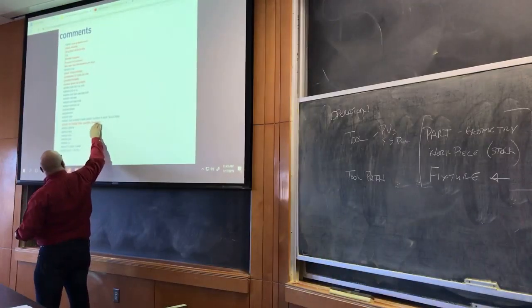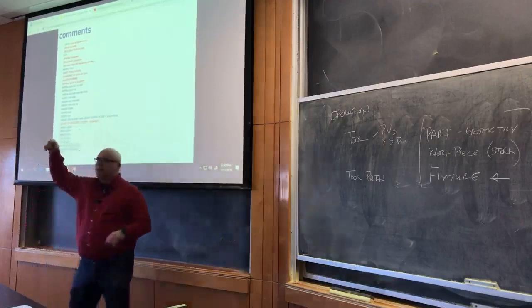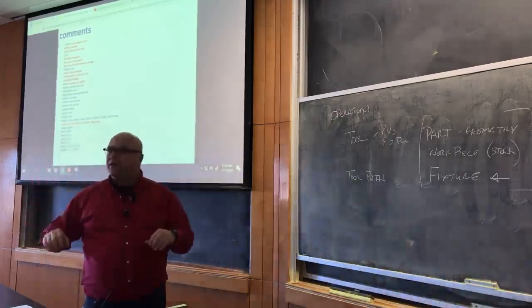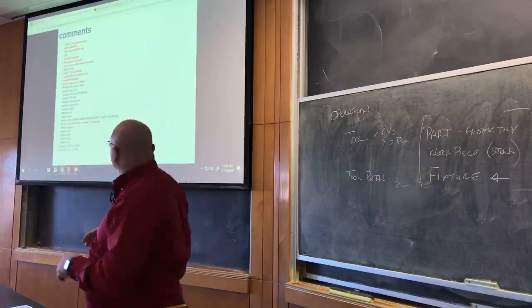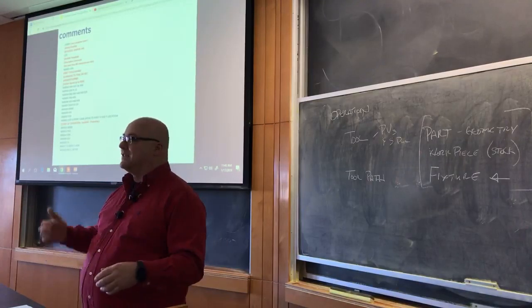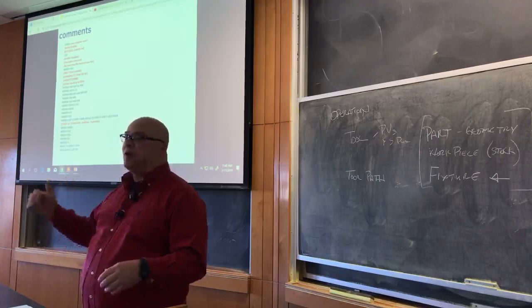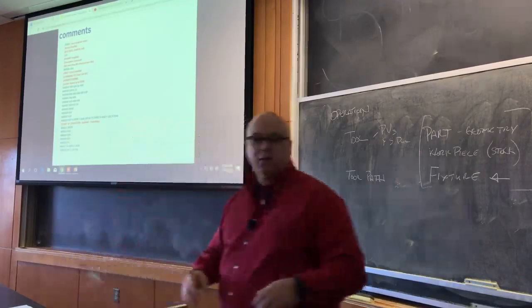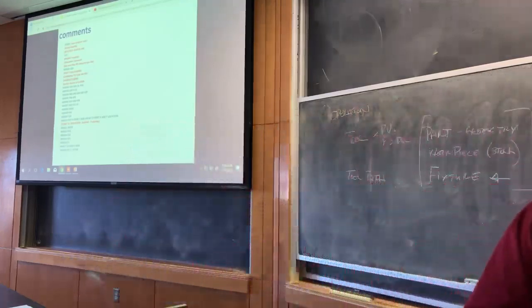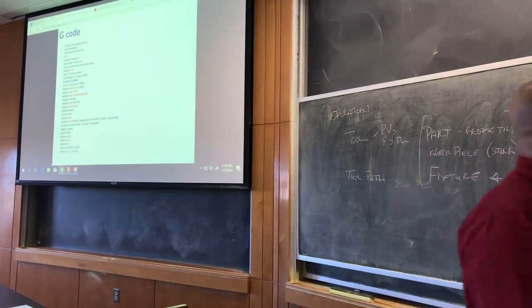Here it says start of operation solid mill pocketing. Each of those operations in a spree has a name. If you name them with something identifiable other than solid mill pocketing, because let me tell you, if there's 67 pockets on your part and they're all named solid mill pocketing, that name is not very useful. But you can find that operation again, and it's especially helpful if you're trying to debug something going on.